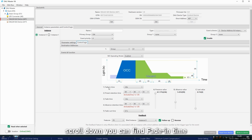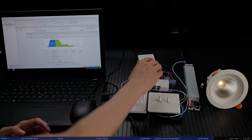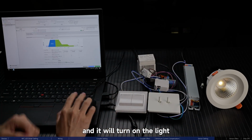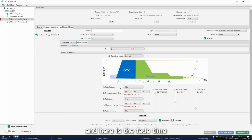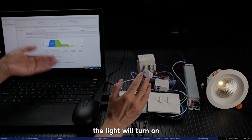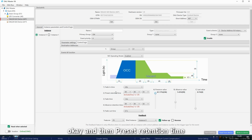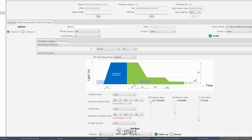And then scroll down, we can find fade in time. It means when the sensor detects motion, it will turn on the light. And here is the fade time. And then presence variable, we set it to maybe 60%. It means when the sensor detects motion, the light will turn on and go to the presence variable. Okay, and then preset retention time.